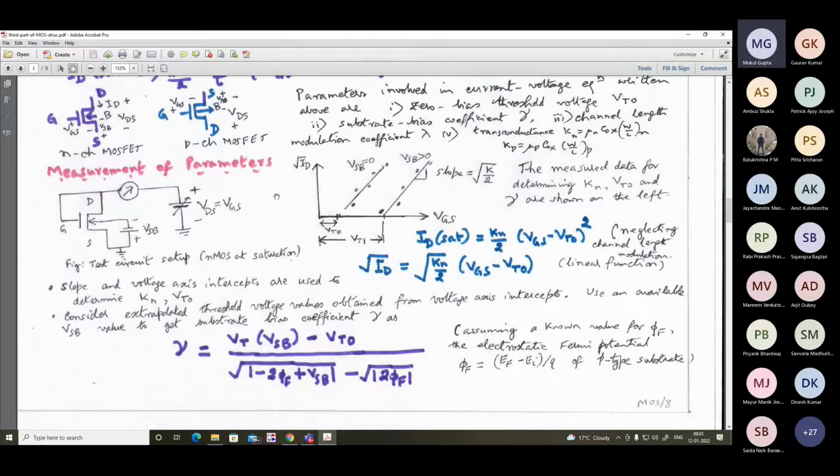But as you go higher up, suppose in a 5-input NAND gate, you have a series placement of 5 transistors in the NMOS path. For the bottommost transistor, the source is connected to the body. But as you go higher up, to the second transistor, third transistor, the difference of source and body potential will rise. So by mistake, this ground should be on the body side, not on the source side.